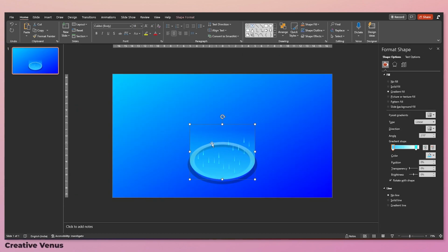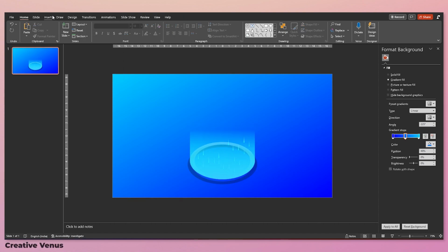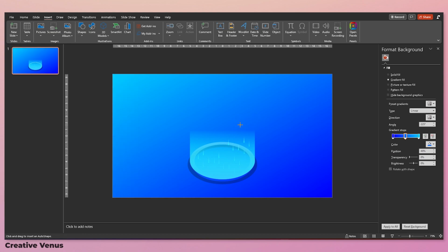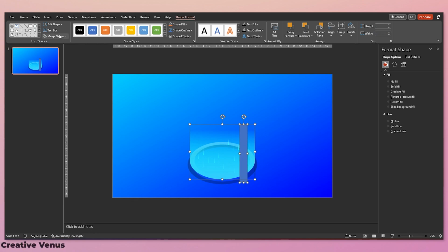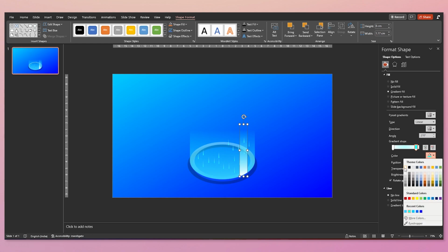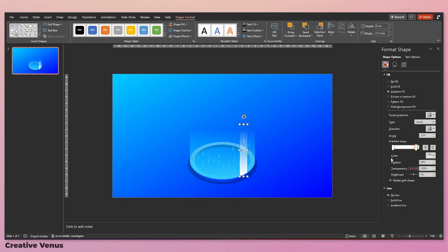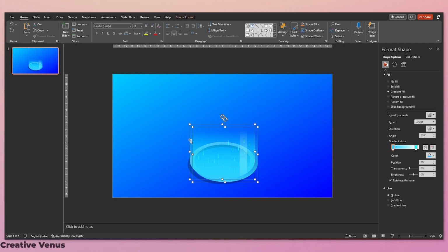So this looks fine. Now duplicate this glow background and align to left and align top. So now we have two copies of it, and then just draw this rectangle and select both the shapes, the rectangle and the duplicated copy, and press subtract, and fill white color or gradient color on this newly created shape and create this white gradient filled with transparency.